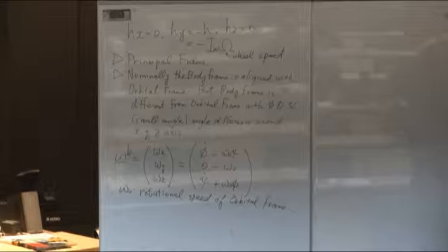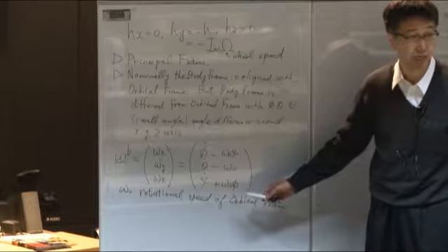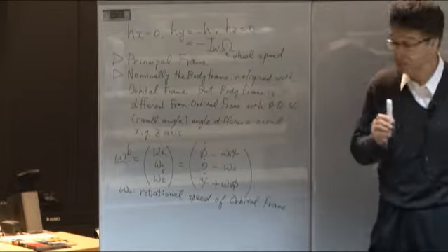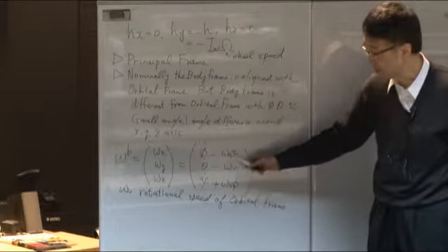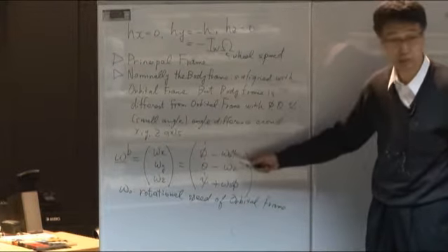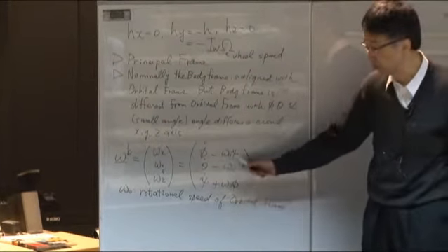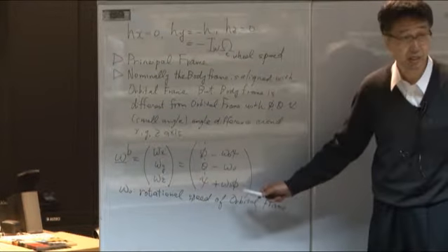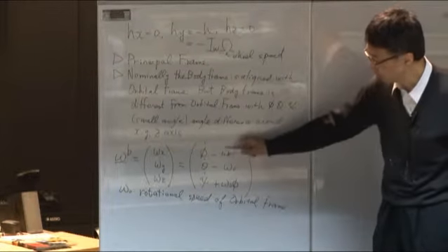And for the spinning satellite case, as I said in my spinning equation, omega x-axis and z-axis are of course coupled. They have some relationship, and this coupling is by way of rotational speed. That is, in that case, a spinning speed, the spinning axis. The spin speed is much faster than the orbital frame rotation omega 0. So for the spinning satellite, the x and z coupling is much stronger.